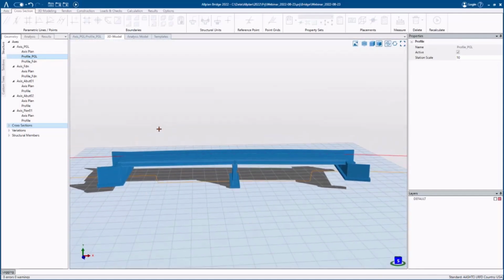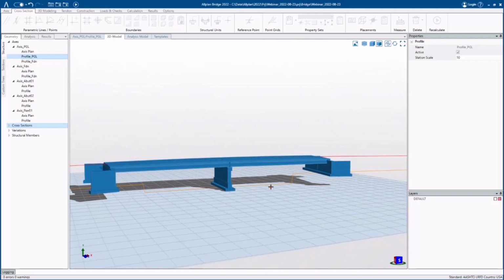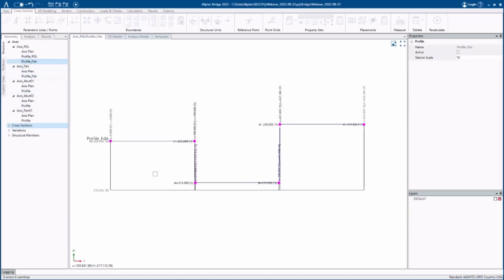I can make changes to the second axis that you see at the bottom of the bridge. So this lighter yellow-orange line is the elevation of my bearing stratum. So that makes adjustments for the site conditions and is what sets the bottom elevation of my substructure elements. So the two abutment footings and the pier footing. And adjust that value as well. So in this case, let's move up that value and say that the bearing stratum is at a different elevation.